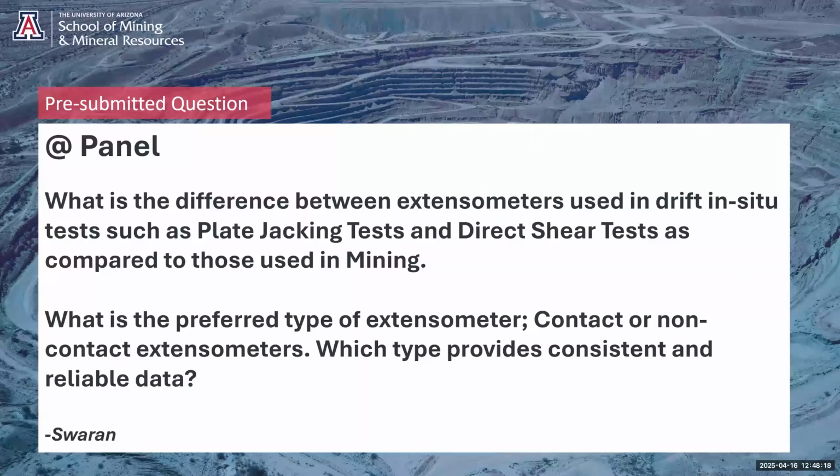So the laser extensometer or a total station, you have a target which is maybe 100 meters away, 200 meters away, whereas an extensometer, with all the mechanical hardware, yes, it can be 100-meter long, 200-meter long, but as you're pointing out rightly, it's compact in the sense that the anchor down the borehole is physically connected to the surface or to another anchor.